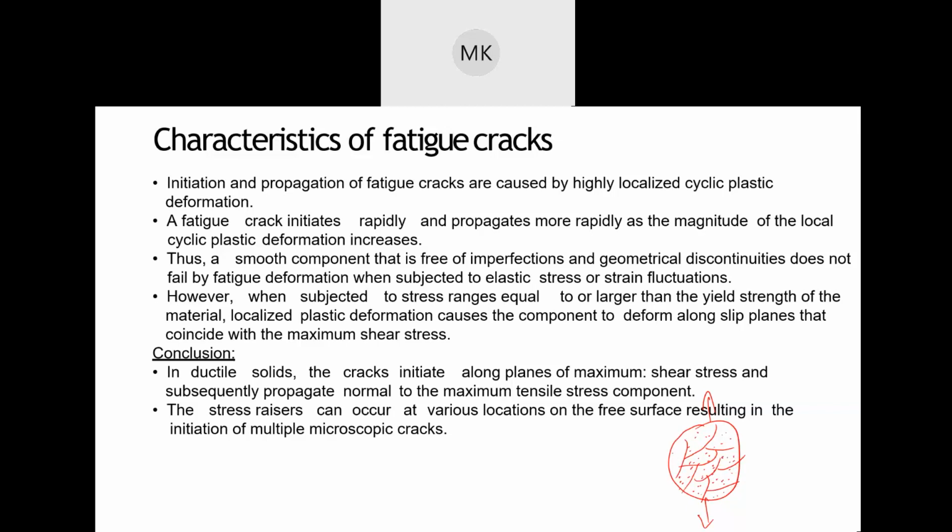And that void is going to be really small as you keep loading it. A couple of voids will try joining to each other to form a small mini crack that happens in the material. And these mini cracks are generated after that at thousand different places.